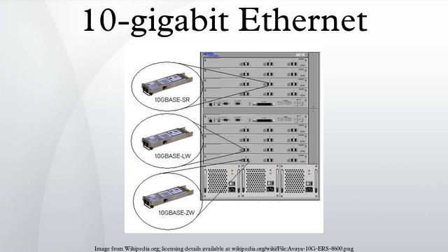10GBASE-T uses the IEC 60603-7 8P8C connectors already widely used with Ethernet. Transmission characteristics are now specified to 500 MHz. To reach this frequency, Category 6A or better balanced twisted pair cables specified in ISO/IEC 11801 Amendment 2 or ANSI/TIA-568-C.2 are needed to carry 10GBASE-T up to distances of 100 m. Category 6 cables can carry 10GBASE-T for shorter distances when qualified according to the guidelines in ISO TR 24750 or TIA-155-A.